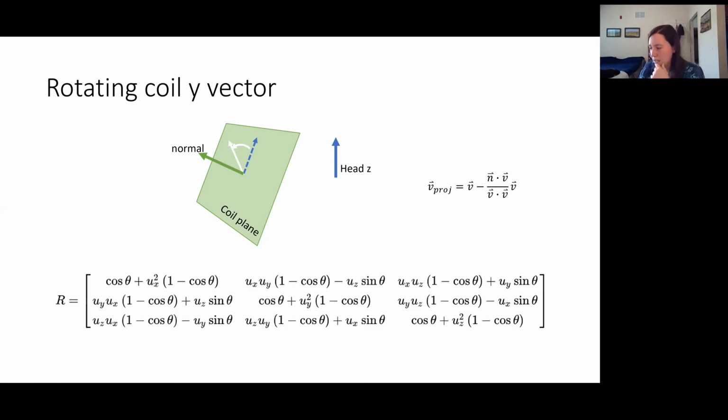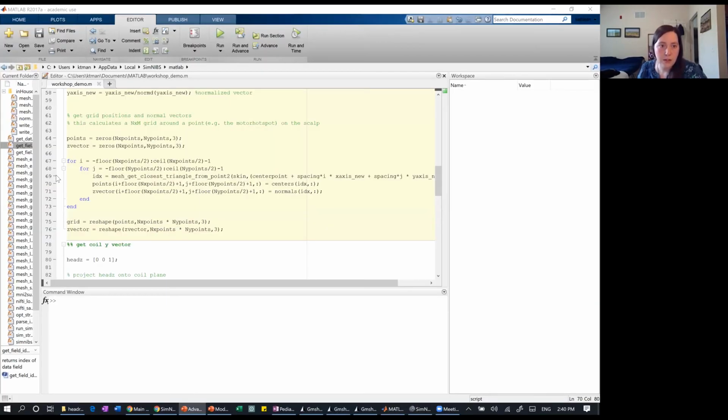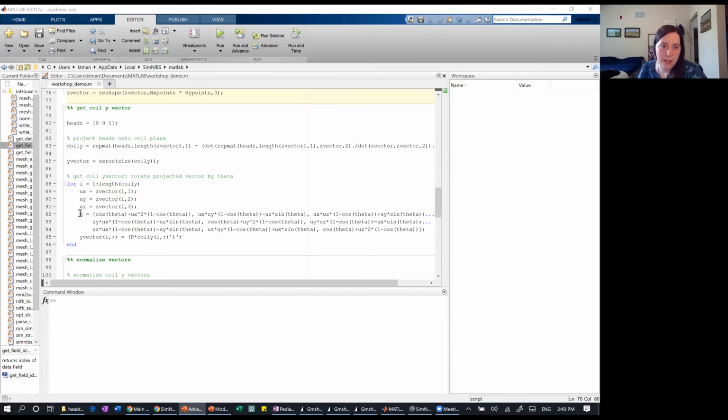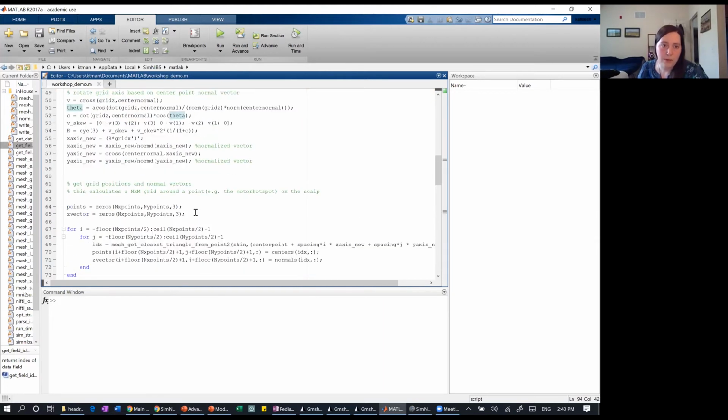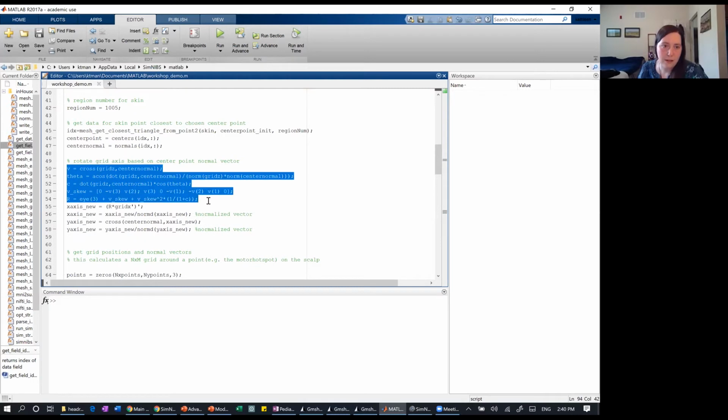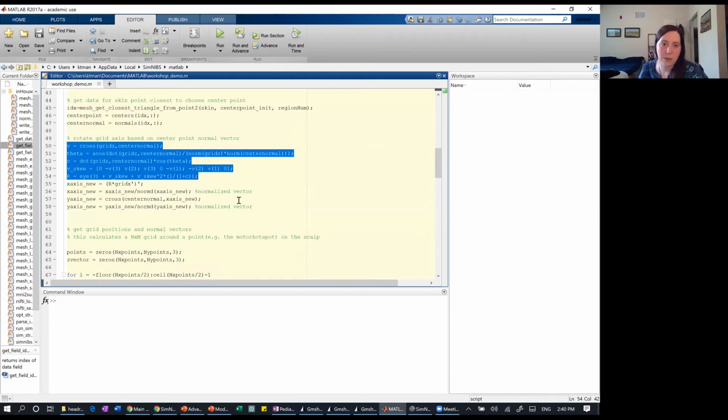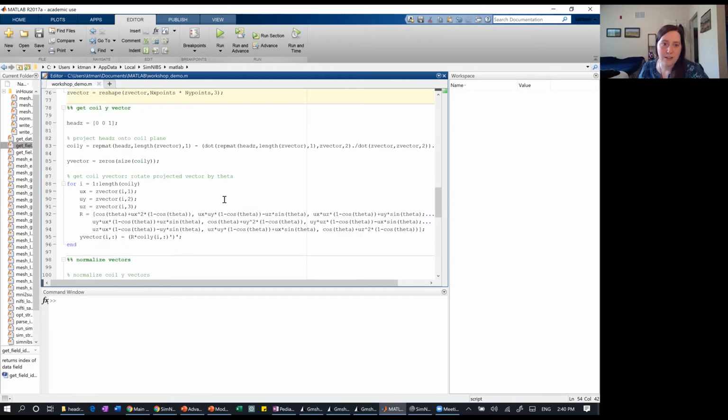In this case, I'm using the expanded formula of Rodrigues' formula, just to show that you can do the same thing in many different ways. This time I'm defining my rotation matrix this way, and previously I had defined it this way. They're the same thing, but as with any type of coding, it all has to do with personal preference, and there's always multiple answers.